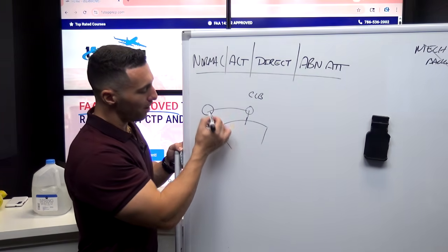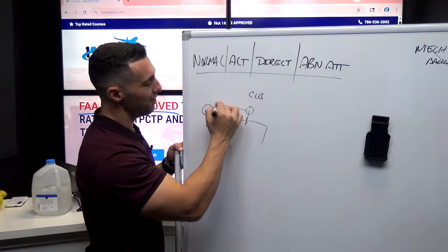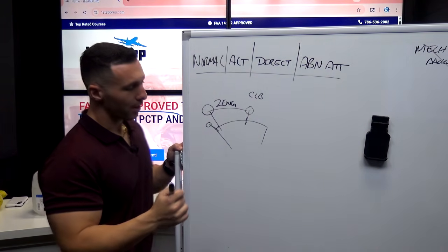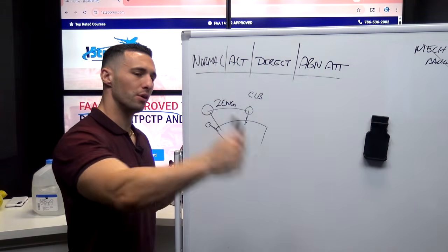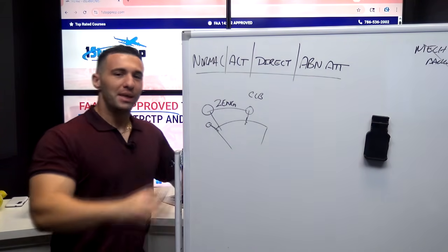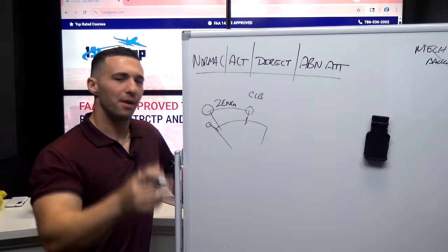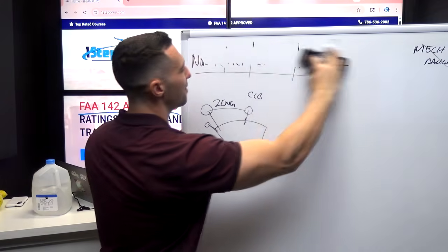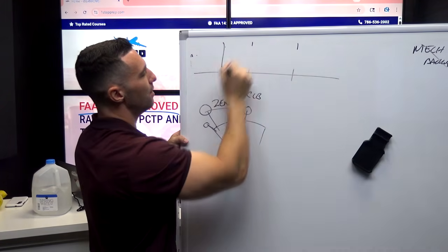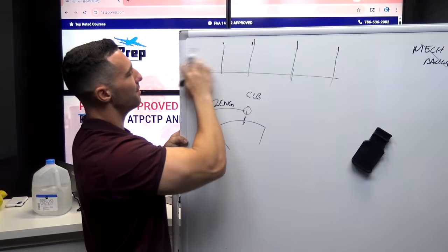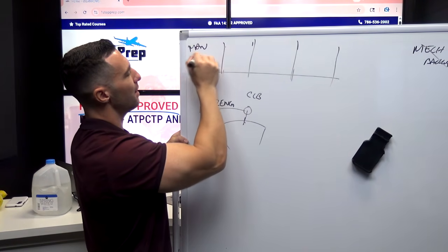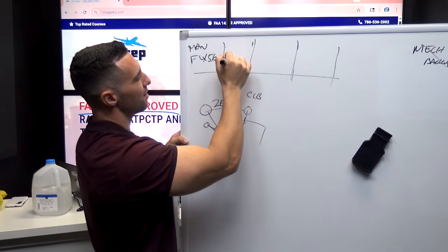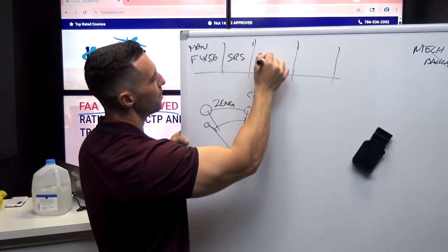Now, if I go just above idle up to and including climb, this is the active range for 2 engines. What happens is, like on takeoff, for example, when we go to TOGA or flex and you start to read the FMA, the FMA says MAN FLEX. If I read it left to right, let's turn this into an FMA up here for the sake of conversation. Auto thrust column far left, right? It'll say MAN FLEX 56, SRS, RUNWAY, auto thrust blue. Something like that.